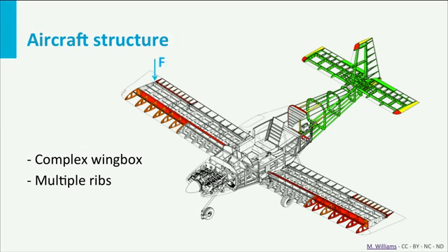When a load is applied at the tip of the wing, the structure should transfer this load to the virtual center of gravity of the plane to make equilibrium with other forces. Therefore, the structure should provide a load path. In this case, first the load is transferred via the rib to the main spar. Next, the main spar transfers the load to the center of the aircraft.